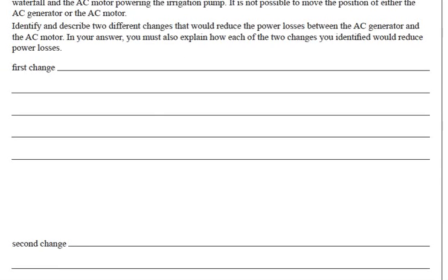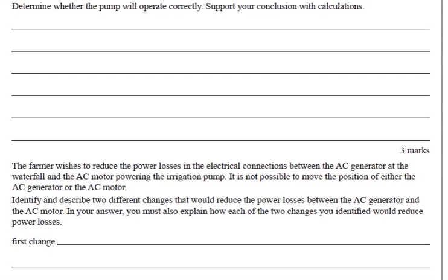C and D. Alright. Determine in this case whether the pump will operate correctly. Support your conclusions with calculations. There's a number of ways of doing this. Is it getting the right voltage? Is it getting the right current? Or is it getting the right power? The way that I've chosen to do it is to see, is it getting the right power?